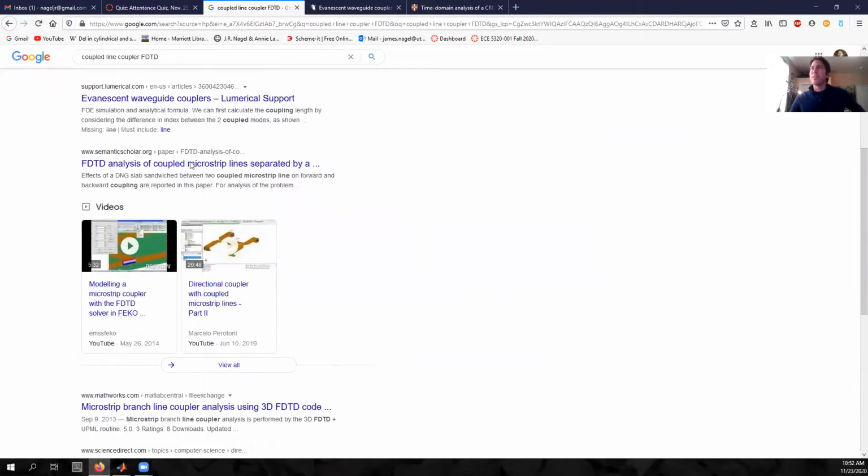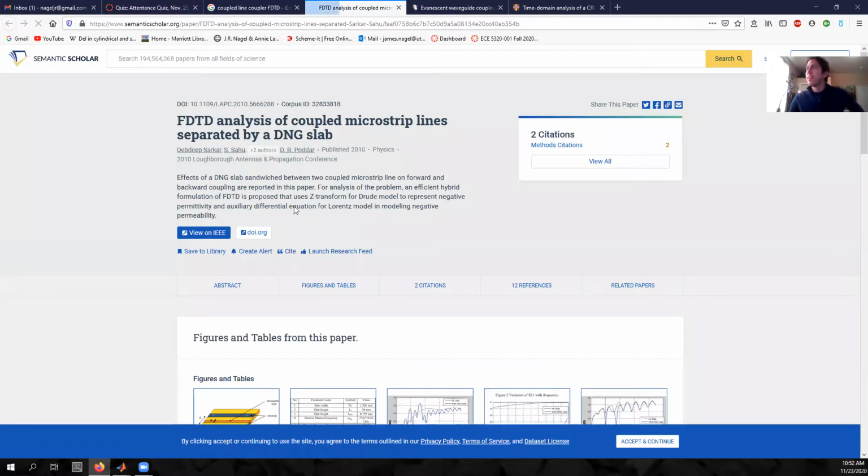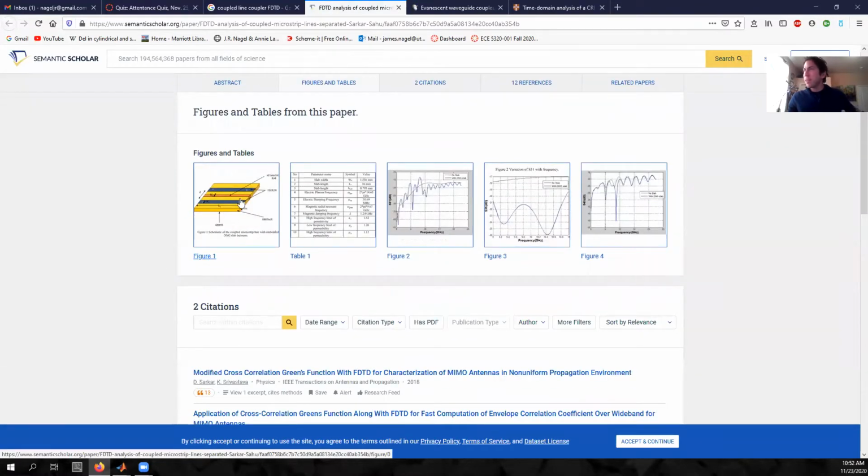But it's interesting when you see, here you go, here's a microstrip version. And from what I could tell, they're doing full three-dimensional simulation of this thing. So I was curious, is it possible to do a very simplified simulation using nothing but the telegrapher equations and the appropriate characteristic parameters here? So that was the idea I was going for today.